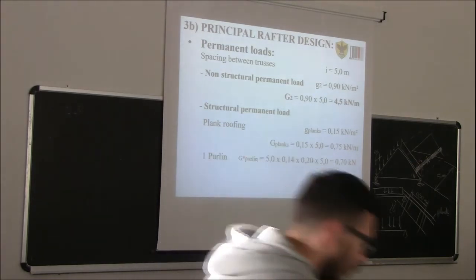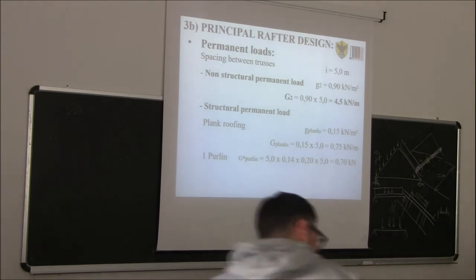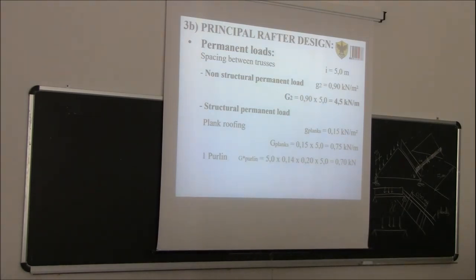Yes, but do we really need to sum all of them and divide by the length? Is there an easier way? Yes, so if you count them, you sum, you divide by the length. We need to count how many purlins are in 1 meter. Let's say in 1 meter, how many purlins can you find?